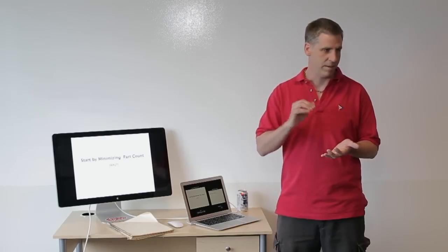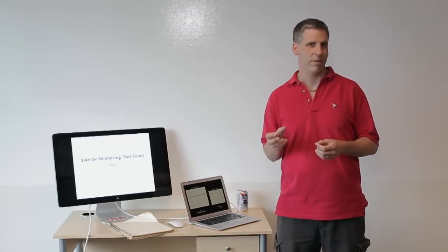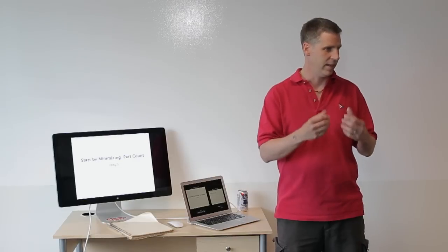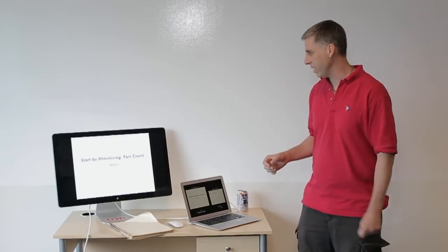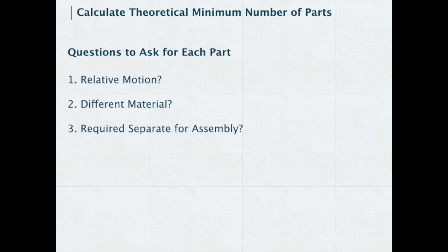You don't need to carry it on the bill of materials. You don't need to pay for it. Your design just gets a lot more efficient. And also it saves a lot of time and effort because you don't need to have an assembly worker put it in place and deal with that. So always thinking about minimizing part count is a great place to start.